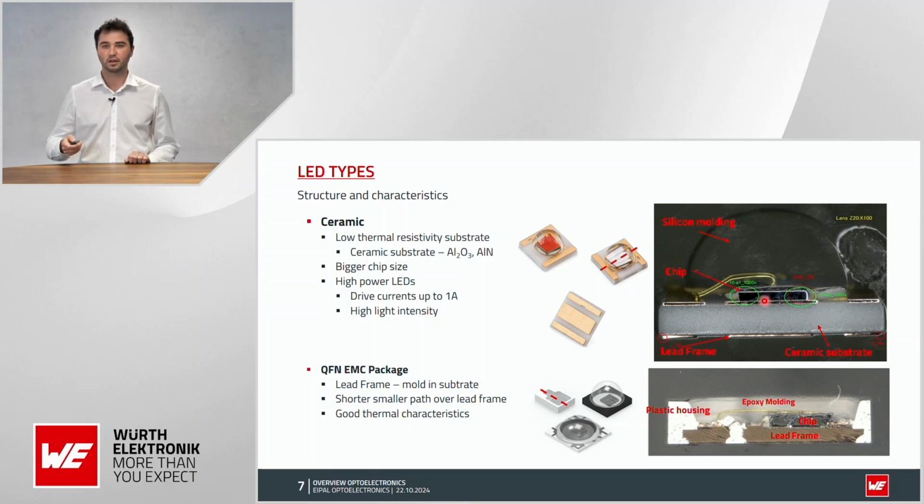Because of this, it's good to make this large chip on a ceramic substrate. This ceramic substrate has really good thermal conduction, so it's really good at moving the heat away from the chip into the underlying PCB. Something similar you can do with these EMC packages. There you have the chip basically directly soldered on the metal lead frame, and then you can also have really good heat conduction out of the package.